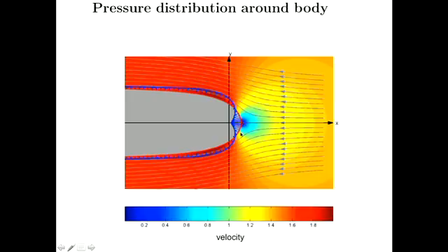All right. And then as we move around that half-Rankine body, that flow obviously accelerates, which doesn't show up very well here, but there's a darker red where the flow accelerates around this body. And you know that where you've got high velocity, you're going to get reductions in pressure. So in that case, the pressure drops below ambient pressure, and you've got this kind of suction force effectively acting on that surface. I don't think suction force is a very good way of describing that, but it's all I can think of for the time being.